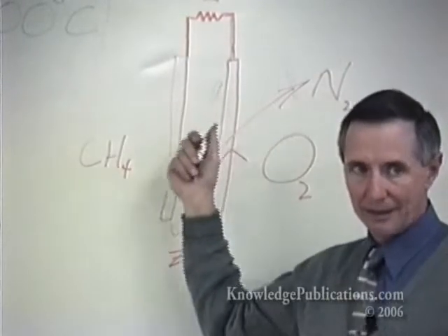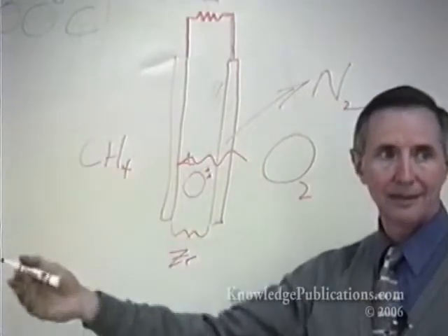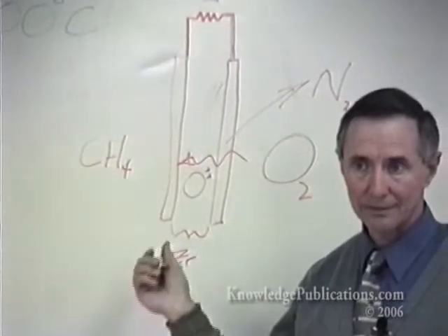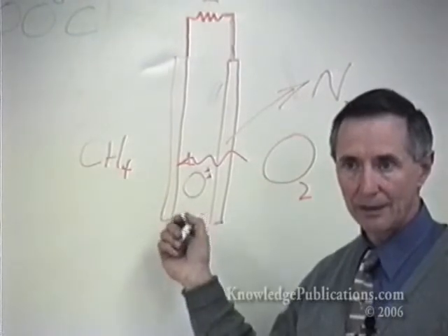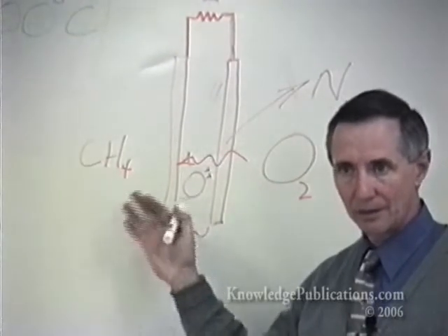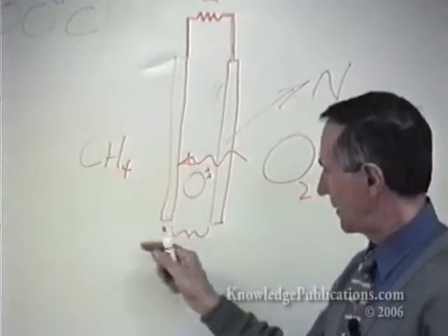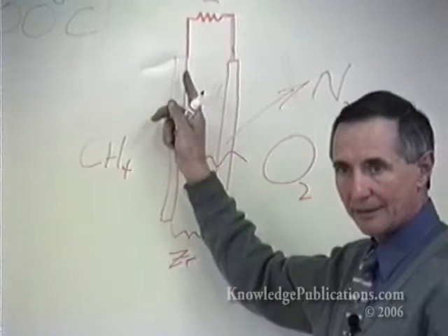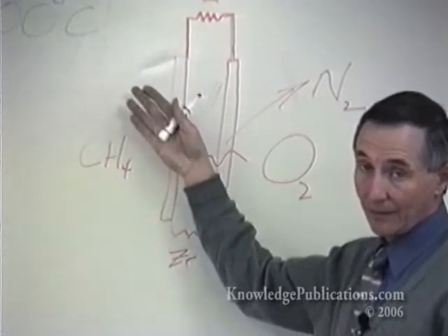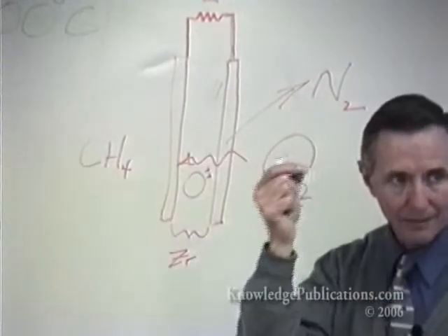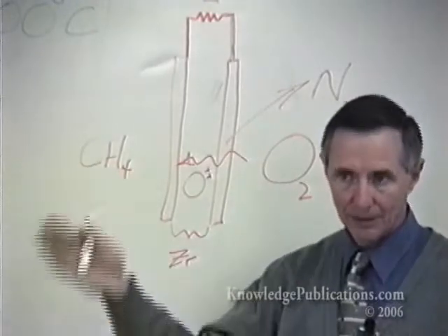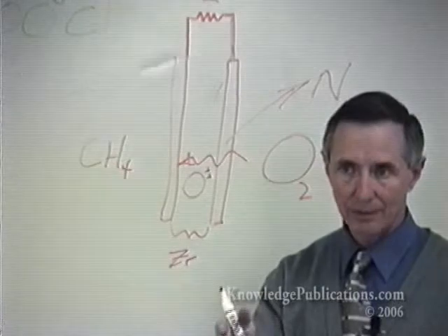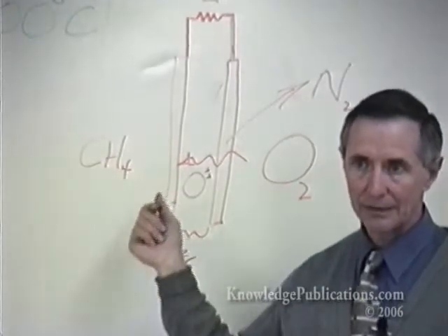So you start looking at things like the silicon compounds that you can dope for the purpose. The trick here is to dope it so that it protects the zirconia, carries the electrons out, and what you try to use is a little bit of platinum group coating, as little as possible, or the refractory metals that are in combination with protective coatings.